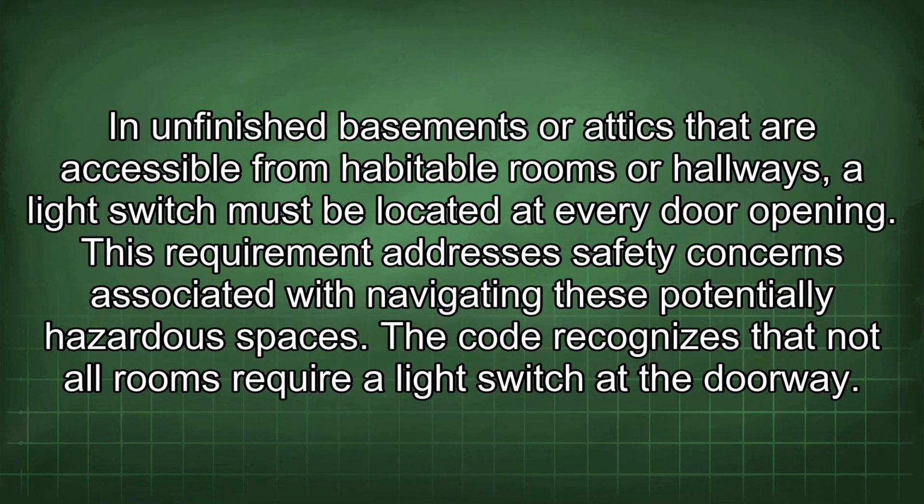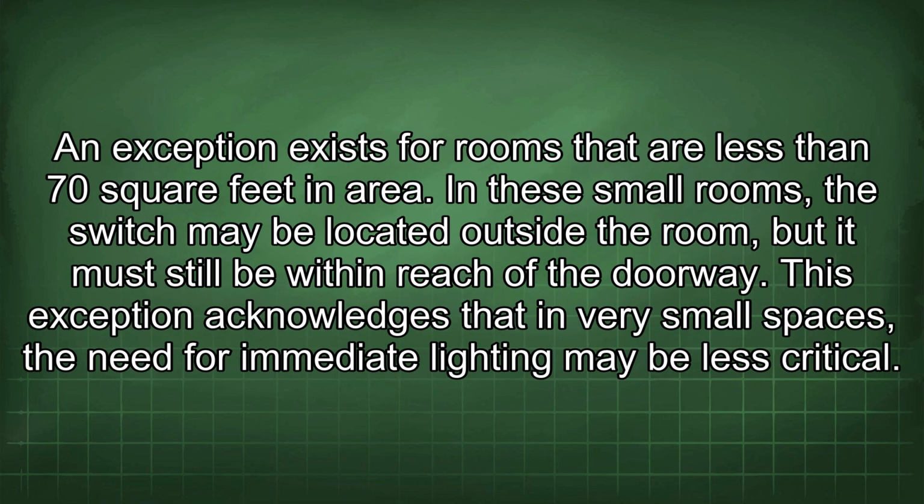The code recognizes that not all rooms require a light switch at the doorway. An exception exists for rooms that are less than 70 square feet in area. In these small rooms, the switch may be located outside the room, but it must still be within reach of the doorway. This exception acknowledges that in very small spaces, the need for immediate lighting may be less critical.